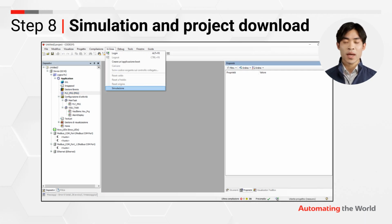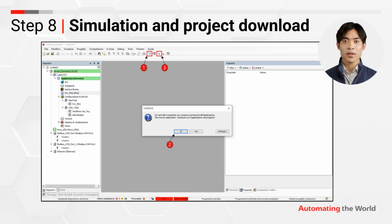Step 8. Simulation and project download. Once you've completed the logic, to launch the development environment in simulation mode, go to the Online option in the top menu and enable simulation mode. Next, we can see simulation mode being activated from the bottom bar of the environment. From this point on, you can continue as if the hardware were actually connected.